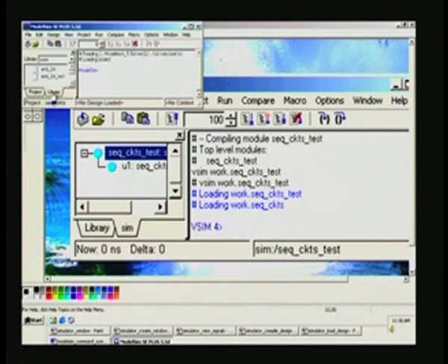Just click on library here. So, you see library work pops up here, and that is what we want. There are other things, say IEEE etc. If you put files in IEEE, any files that are created here will be written overwriting some of these system files. That will have a corrupting effect on its function.